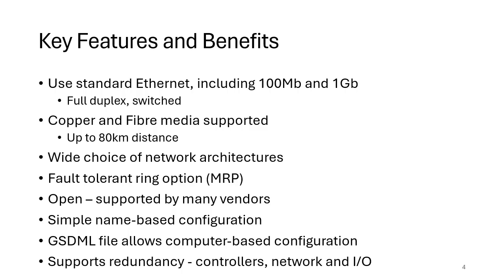Some vendors support multiple Ethernet protocols anyway. Some support Ethernet IP and PROFINET and others. Some only support PROFINET as their I/O, but it has wide support by many different vendors. And it's interoperable. In theory, a device from one vendor will work with a device from another vendor, and that usually works in practice as well, because the PI organization does have regular interoperability testing where people can turn up, put their devices or their controllers on the network, and test them with other people's devices to make sure it works. If a device doesn't work for some reason, then the vendors should work together to make it work, because it is intended to allow interoperability.